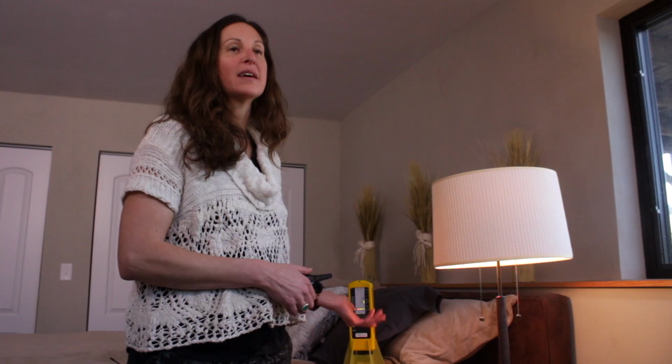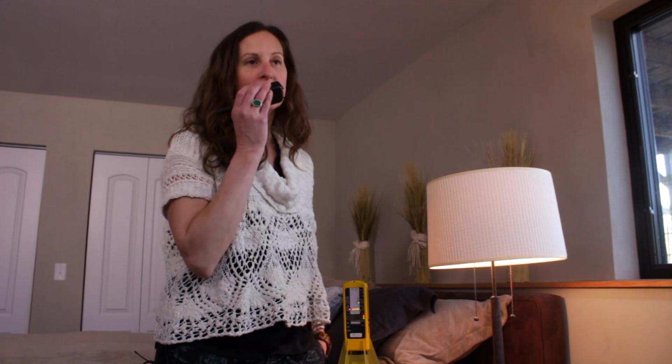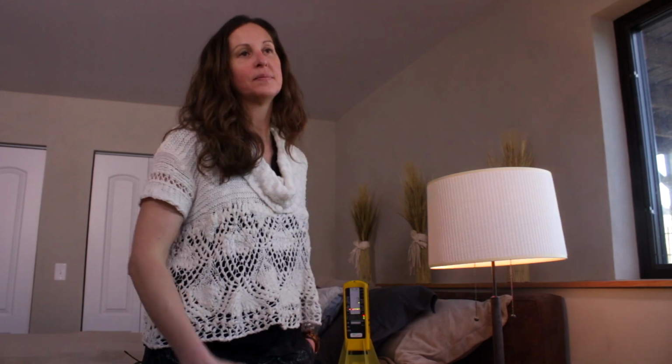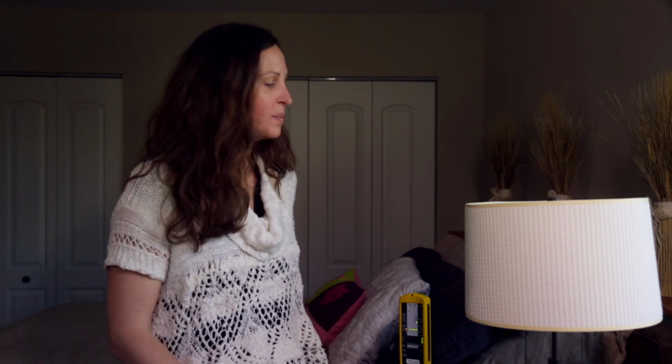I have an assistant out at the panel ready to turn off those breakers, so I'm going to ask the assistant to do that at this time, and you'll see the impact on the meter. Can you go ahead and turn off the breakers, please? So the breakers have been turned off, and you can hear and also see that the meter has gone down to 0. In this particular case it was 2 breakers, because there were 2 circuits that were impacting the bed within the 6 to 8 foot range. As you can see again, the meter says 0. So from an electric field standpoint, this would be a safe sleeping area.